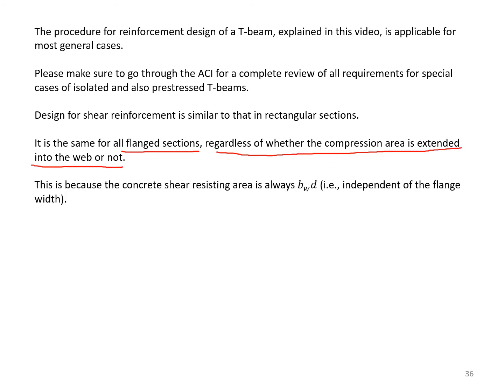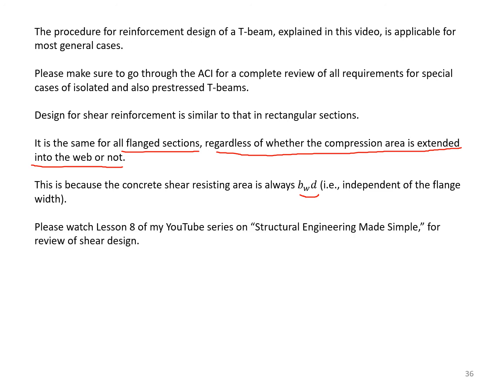This is because the concrete shear resistance area is always BW times D. In other words, it is independent of the flange width. Please watch lesson 8 of my YouTube series on structural engineering made simple for review of shear design.